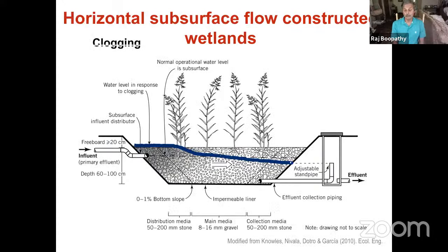And this is a horizontal flow wetland. So you can see the system is a little bit longer. Okay. If you look at it, it has influent, and it has this filtration permeable layer. It has an impermeable liner, so there is nothing seeping into the groundwater. And then it percolates down, and your plants are going to take care of nutrient uptake, and then the effluent comes out, and treated waste is collected in a pond before it is being discharged.